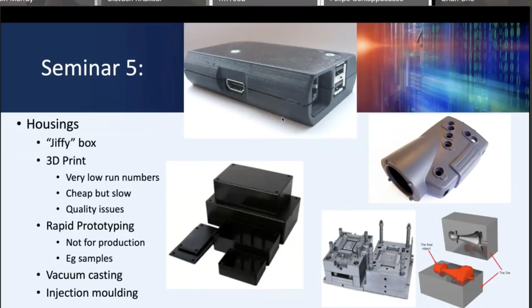Now, I've picked a particularly bad 3D print here for a reason, to show that the quality is not always great. Here we can see the individual layers of the print, so it's a rough sort of finish. That textured top is not done as a design improvement. It's actually the pattern you get from where the case was sitting on the 3D printing table. We've got some warping. So if we look here, the gap here is slightly different and increases in size here, which is very common in 3D printing. And generally, it's a nice shape. It's the shape we want, but the quality of the case isn't great.